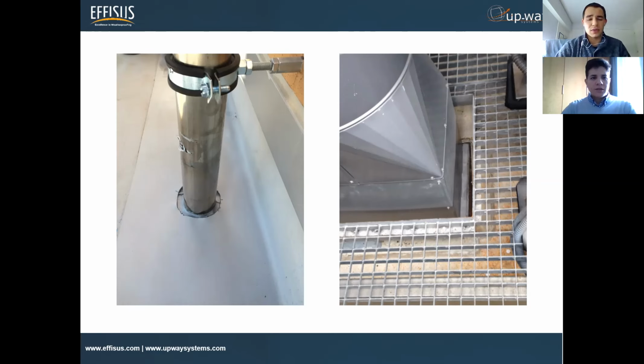Absolutely. That's why we see here, when it's possible, which is not always the case, next to the wall, this pipe is attached to something, hanging to something to avoid these vibrations. But in many of the cases we see outside, it's not possible to have this sort of hanging. So depending on the type of penetration and the height, these ventilation pipes are constantly moving and vibrating in the wind.